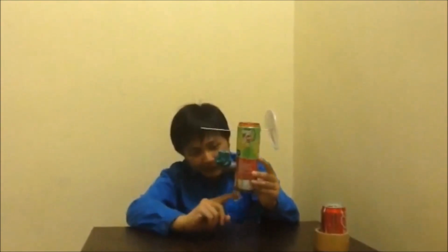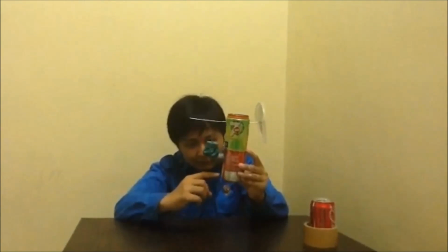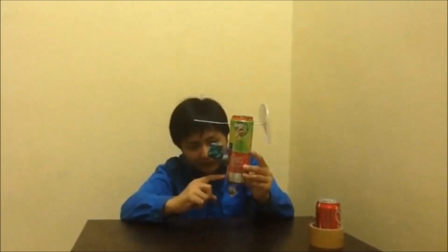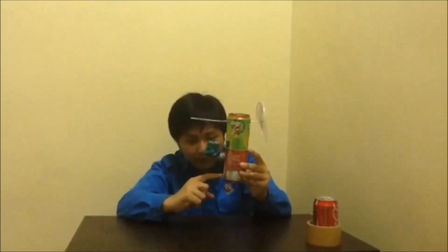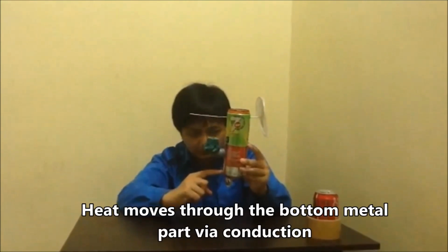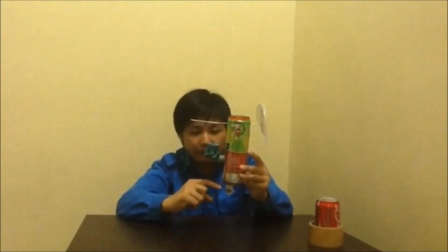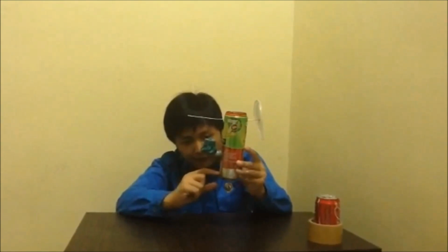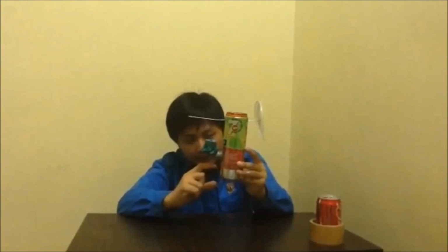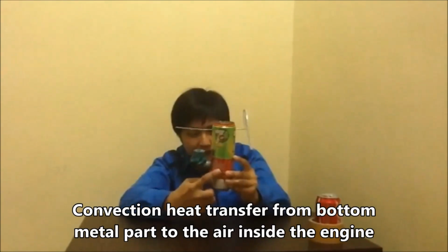Second, the heat will be transferred from this bottom plate to the upper side of the bottom here inside the cylinder by means of conduction, heat conduction. After the heat flows through the plate, it will be transferred again as convection heat transfer inside the cylinder.